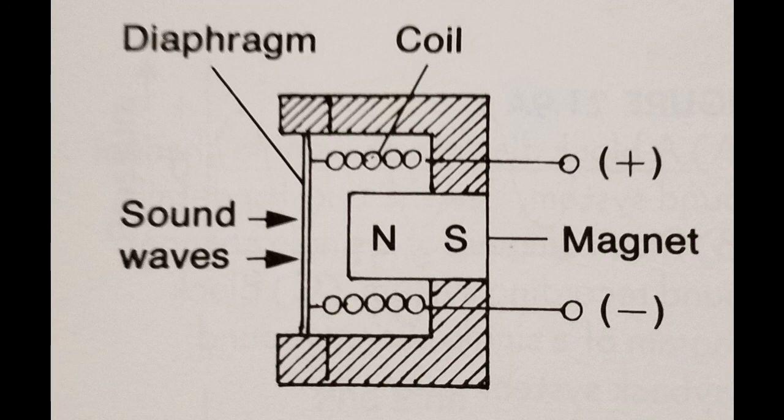One end of the coil is firmly attached to the diaphragm of the microphone, and when sound waves strike that diaphragm, both the diaphragm and the coil start to move back and forth, thus generating the induced current that mimics the frequency and intensity of that particular source. Dynamic microphones have a very good frequency response. They are fairly rugged and are suitable for on-stage use and even in recording studios.